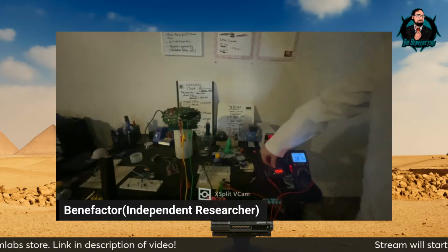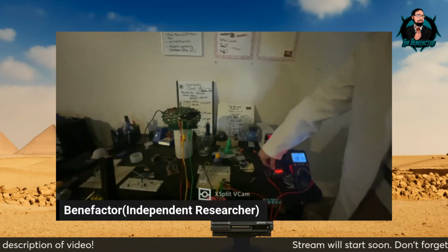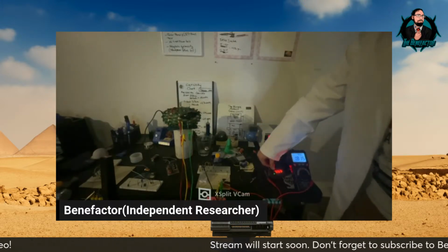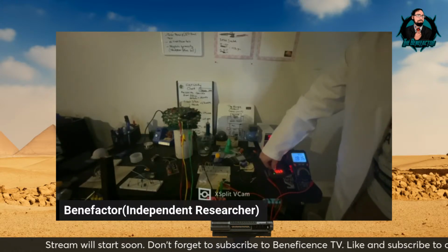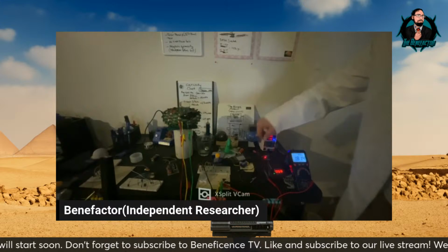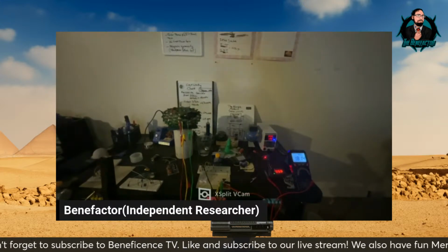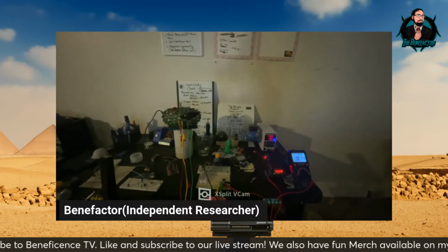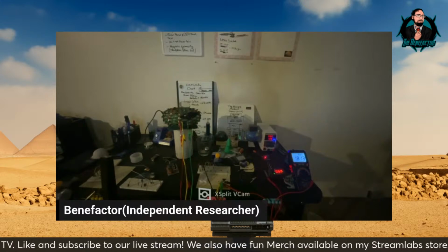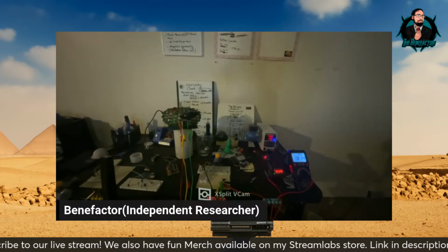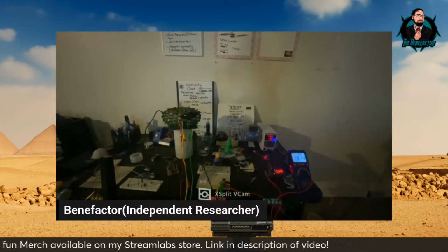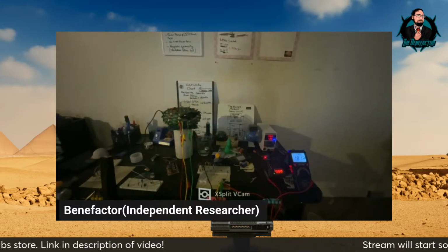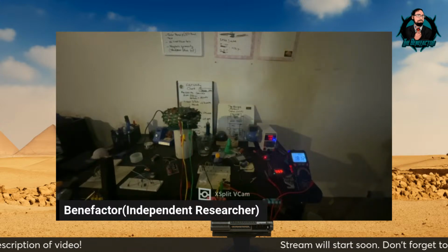And then we're going to change the frequency. You might be able to lower your frequency. Can you lower it? Does this have a duty cycle setting and a frequency setting on the PWM? It does. You can set the low percent and the high percent for the duty. You can set the frequency from 1 kilohertz to 20 kilohertz, in 1 kilohertz intervals, I think. Put it at 1 kilohertz with a 90% duty cycle, and there you go.